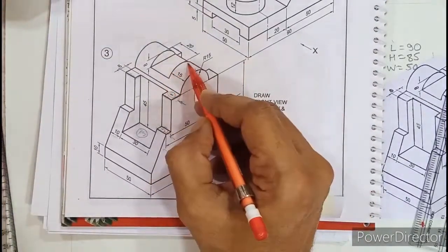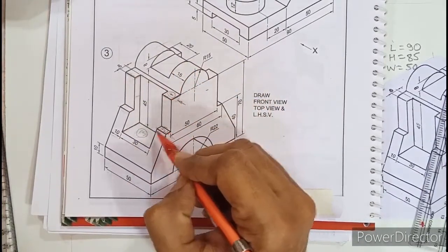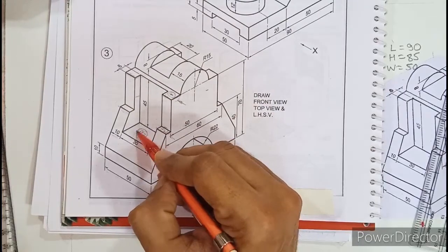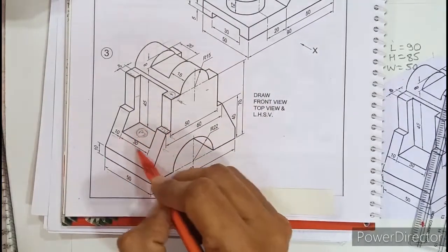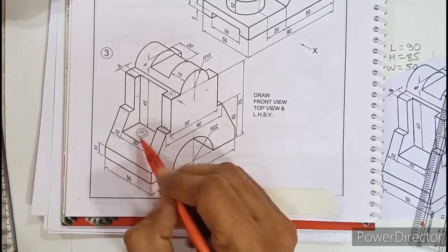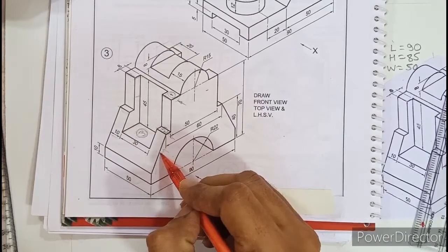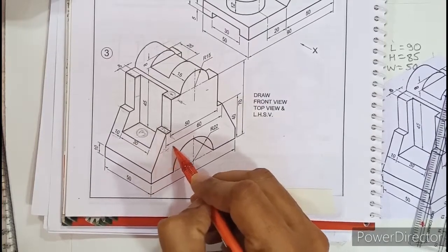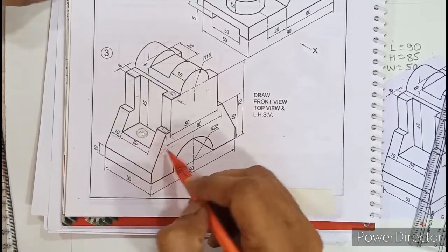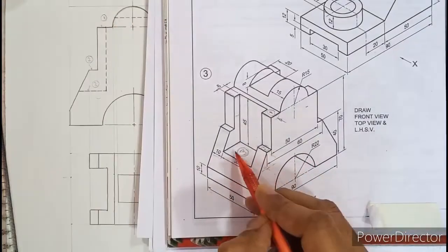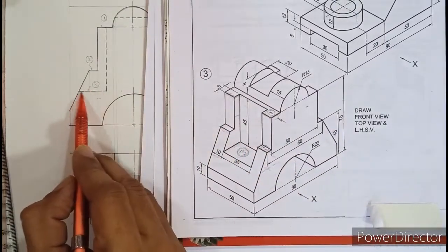So first we have developed the circular surface, then we developed this C type, then the second shoulder. Now comes the third one. The third one is a rectangle of width 30. So the width is 30. The length is unknown, but you can make it out from the front view. In the front view we have drawn a hidden line corresponding to this edge. So that edge will give you the length. If you compare, this edge is the same as this hidden line that we have drawn.